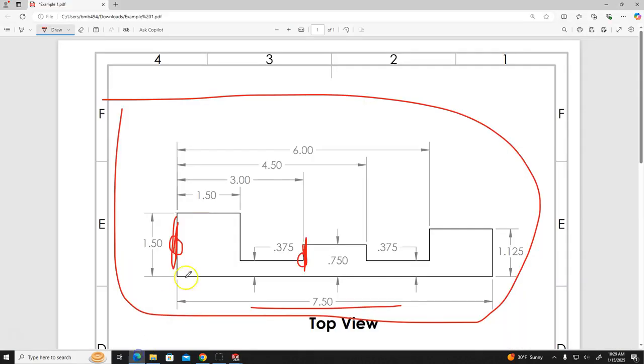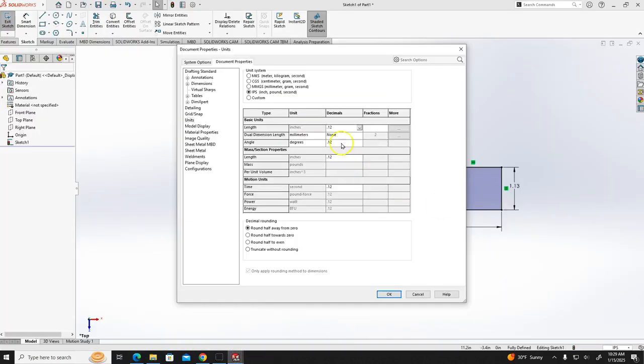If you go to our sketch, this particular dimension has a precision of 3 decimal places, so you have to change it to that, maximum 3 decimal places. You can do this for all dimensions, or for the length only, because in this sketch you don't have any angle dimension right now.